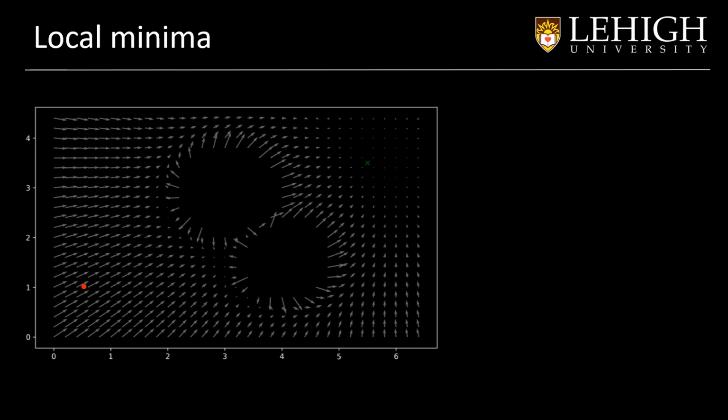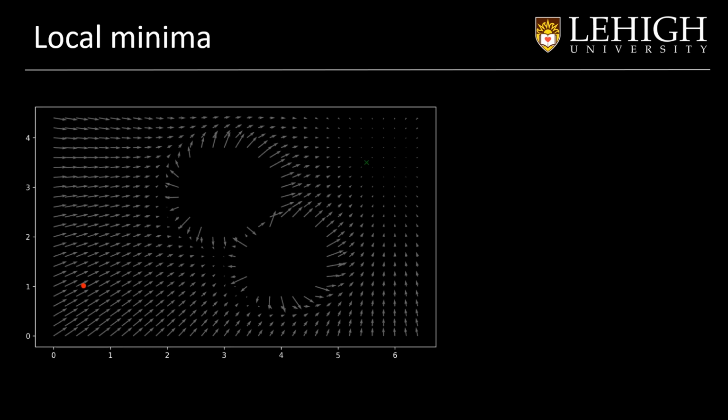The method seems very nice, and actually it's pretty simple, but it has a downside. The main problem here is that we can fall in local minima. In some cases, we will fall into a point where the robot cannot move forward towards the goal. If we see this example in one dimension, it will be something like this.